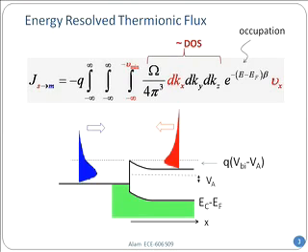Notice that if an electron is going from, let's say, right to left in the x direction, then it has a chance that it will go over the barrier and will contribute to the current. But if I had an electron which is going along the y direction, perpendicular to the junction, well, it can keep going forever as long as it likes, but it will never cross the junction, so it will not contribute to the current, right? And similarly in the z direction, the electron could go forever, but because it is never crossing the junction, it is not going to contribute to the flux.